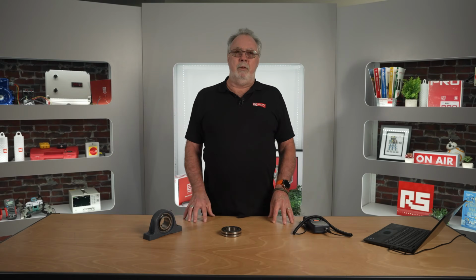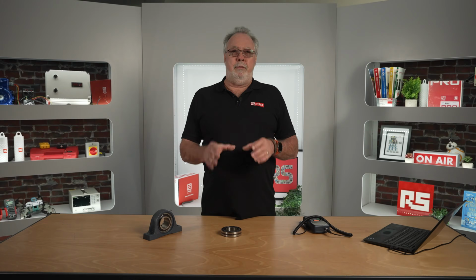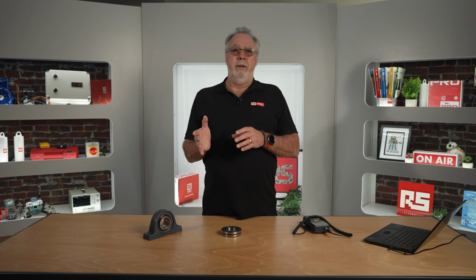Having discussed a handheld monitoring system, you get complete systems which look after the whole machine. These systems have a green, yellow, red traffic light warning system. It's preferable to look at yellow, not wait until it gets to red. If it gets to red, you may already have consequential damage to some other parts of the equipment.